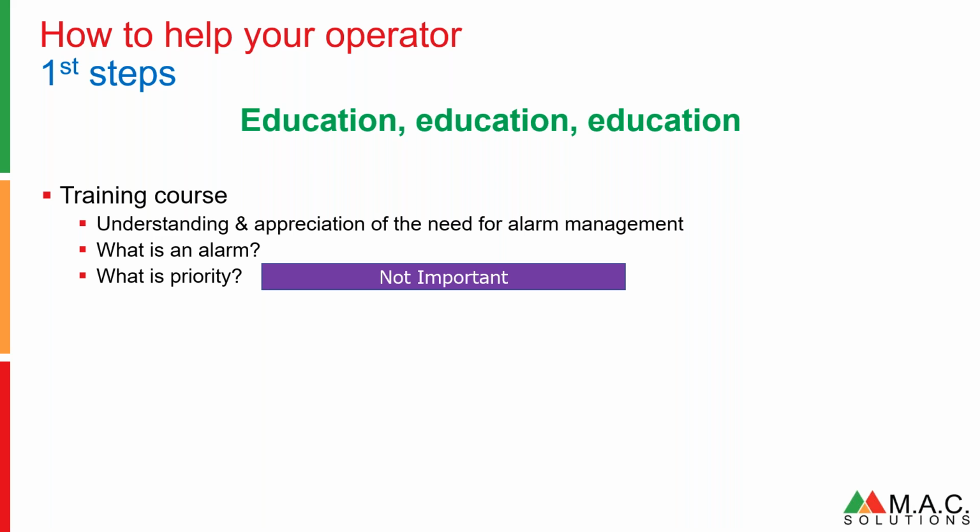And it was flashing. I said, acknowledge that alarm, would you? Humour me, please. They acknowledged, and around about 10 seconds later, the alarm came back again. I said, acknowledge again. It came back in about 10 seconds. They had an alarm happening once every 10 seconds, approximately. That's 6 alarms per minute. If we think about the alarm rates we all quote is alarms per 10 minutes, that's 60 alarms per 10 minutes. We try and get things down. The ideal is less than 1 alarm per 10 minutes. They had an alarm, one alarm, that was generating 60 alarms per 10 minutes. They didn't know what it was.